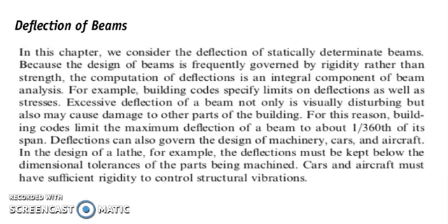Because the design of beams is frequently governed by rigidity rather than strength, the computation of deflection is an integral component of the beam analysis. So basically, we have to take note that in the design of beams, it is governed by rigidity rather than strength. So what's the difference between rigidity and strength?